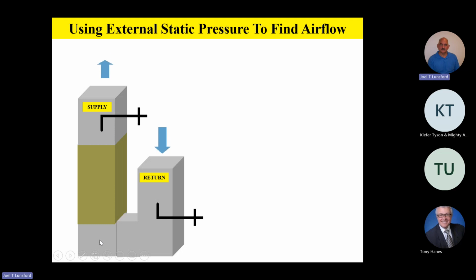That's just good practice. If you don't have a filter right here, but you do have a filter someplace up here, maybe in a main filter grill in a hallway, then go ahead and take it right here where we have it on the return static, and the filter will automatically be part of that airflow measurement. So just be aware of those things, that filters will have some pressure drop across them. So just consider those things.